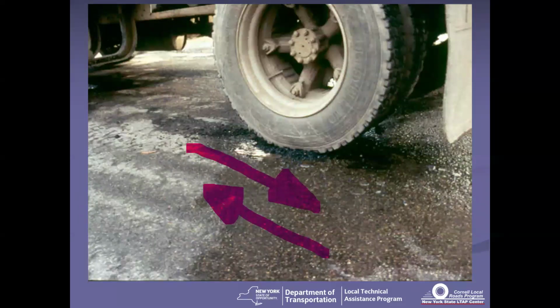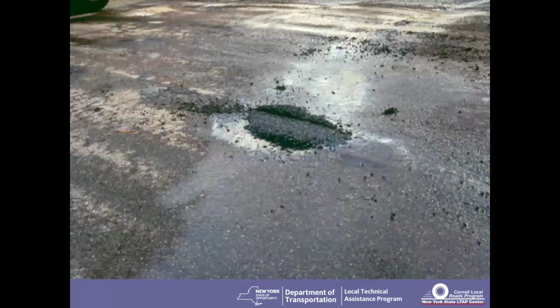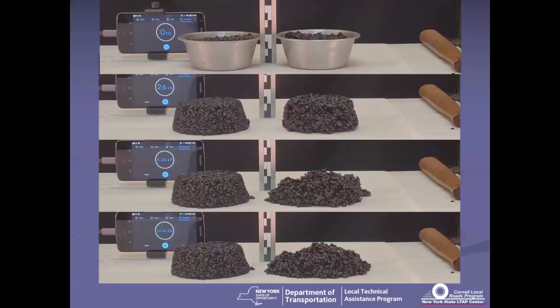It's a pressure activated polymer, just like some pressure activated tapes you would see in a conference room where you want to keep your wires covered. Use a pressure activated tape. You just ride your hand over the top of it and it sticks to anything. That's the same thing that's happening with this material. With a truck tire moving back, pull forward, and you've got your filled hole. And you're good to go other than scrape the edges off. And you've got your pothole filled, and that should take care of you for the rest of the season.